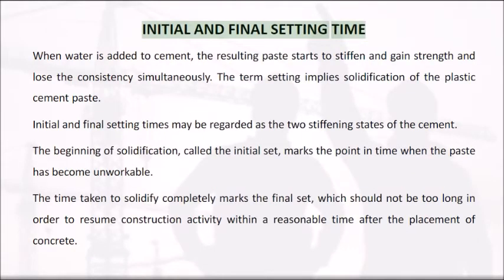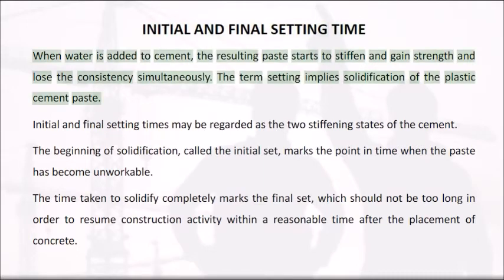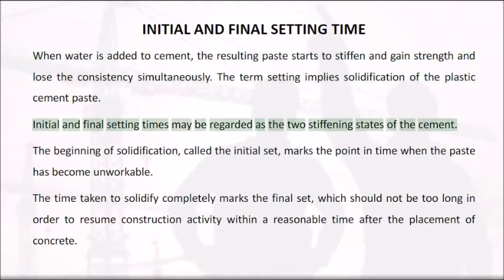Initial and final setting time. When water is added to cement, the resulting paste starts to stiffen and gain strength and lose consistency simultaneously. The term setting implies solidification of the plastic cement paste. Initial and final setting times may be regarded as the two stiffening states of the cement.